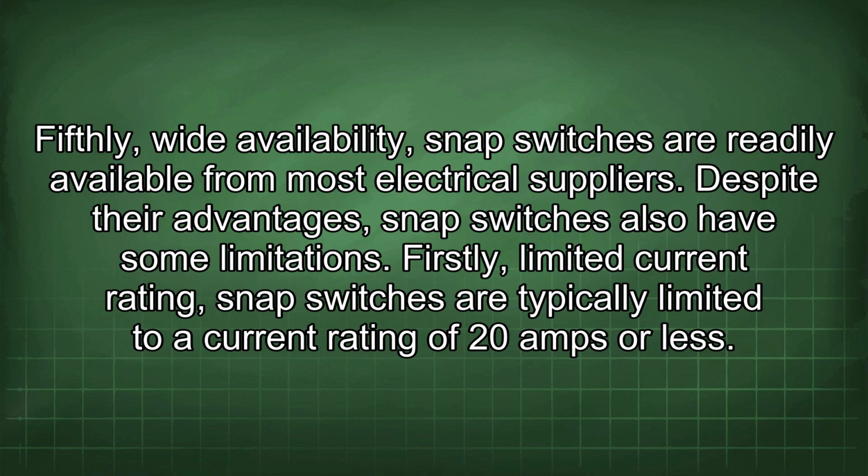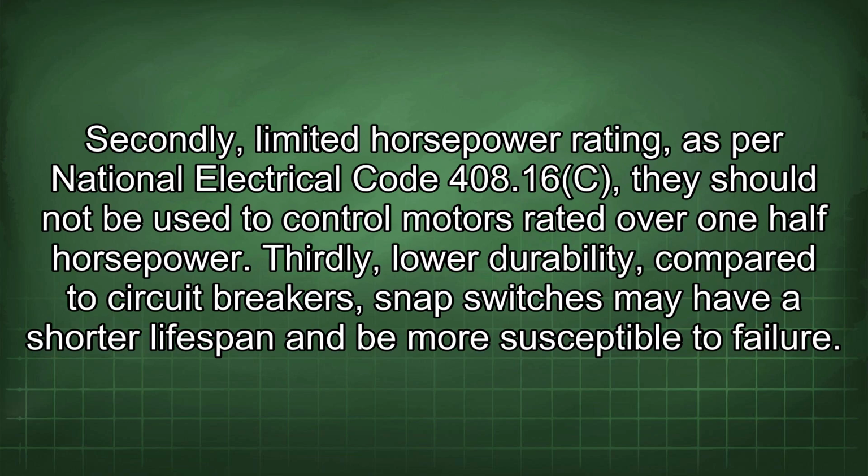Despite their advantages, snap switches also have some limitations. Firstly, limited current rating. Snap switches are typically limited to a current rating of 20 amps or less. Secondly, limited horsepower rating. As per National Electrical Code 408.16(C), they should not be used to control motors rated over 1/2 horsepower.